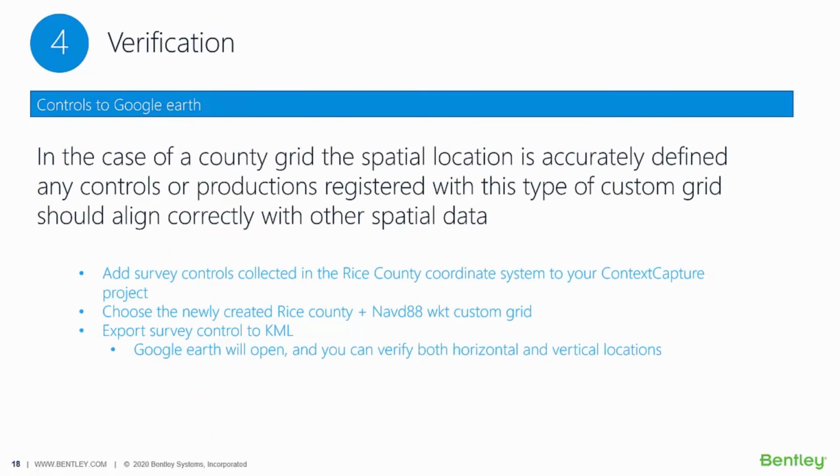The last thing we want to do is verify that our coordinate system is in fact accurate. Now, ultimately, the best way to verify this would be to generate a model and bring it into CAD software that also has the same coordinate system, and import the same ground control that we just added into that CAD software and make sure everything lines up on top of our reality model. But because we don't have that when we're just working through a project,